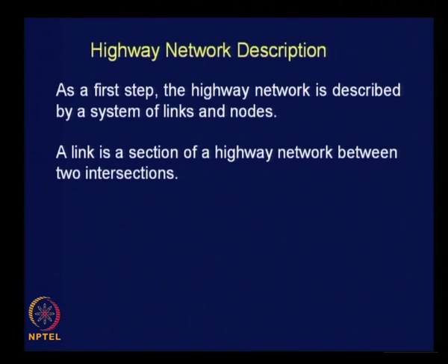In a road network you may have intersections, right, crossing roads, right. The stretch of road between consecutive intersections is termed as link. Okay. You have Madhya Kailash intersection, then there is a Kotturapuram road junction in front of IIT, isn't it? The stretch of road between Madhya Kailash and IIT is one link. Stretch of Sardar Patel road over this particular portion is one link, right.